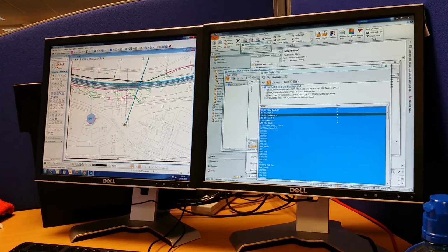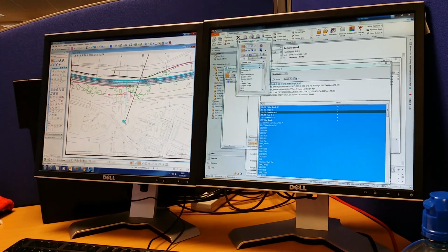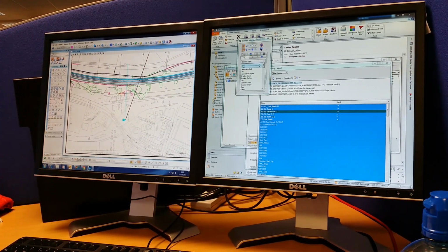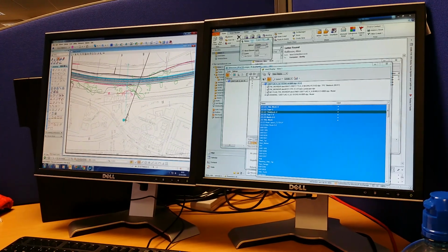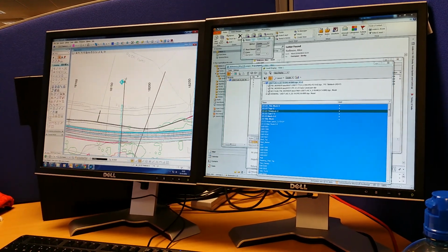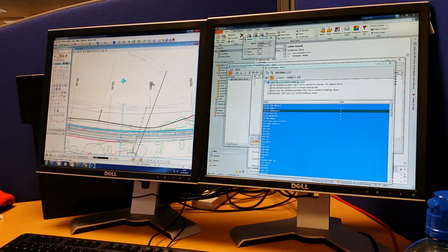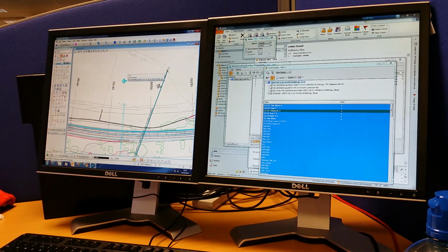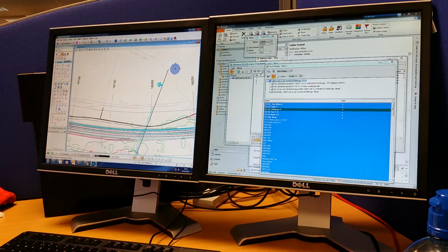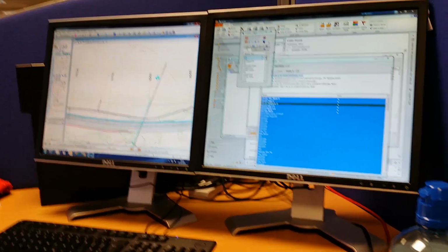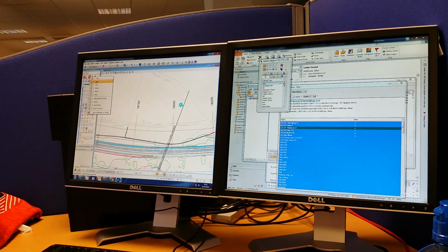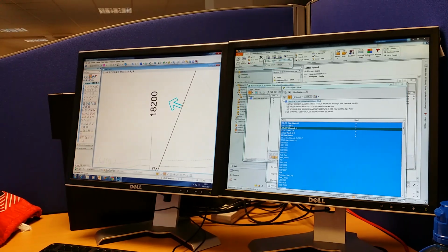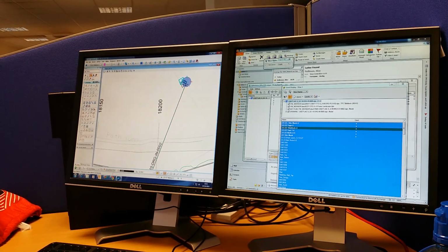Off the end point onto the line, and then while it's still highlighted, select rotate by 3 points. So from that point to that point, which is what you want to rotate. That's what you're rotating to. Okay. Deselect everything. Obviously you can move that to the end of the line. Selecting move, it's just using the endpoint with snap points as you've used previously.